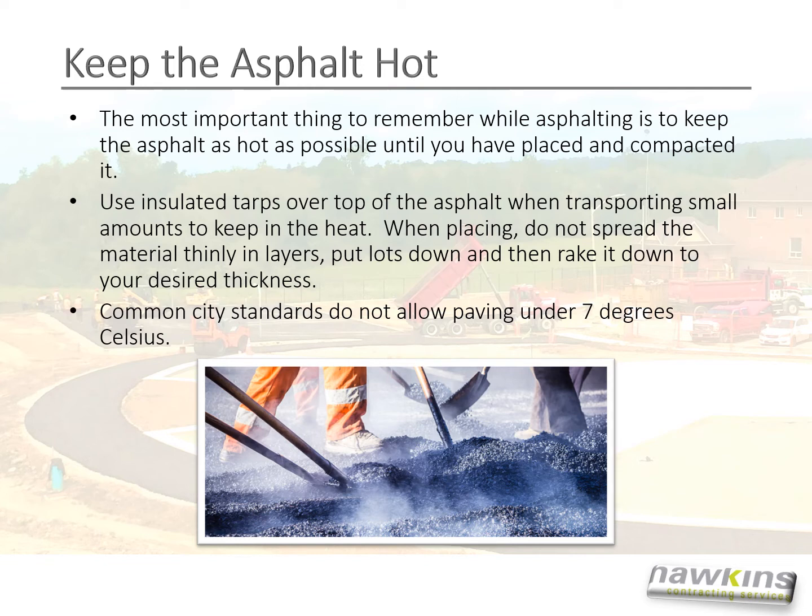Keep the asphalt hot. The most important thing to remember while asphalting is to keep the asphalt as hot as possible until you have placed and compacted it. Use insulated tarps over top of the asphalt when transporting small amounts to keep in the heat. When placing, do not spread the material thinly in layers. Put lots down and then rake it down to your desired thickness. Common city standards do not allow paving under 7 degrees Celsius.